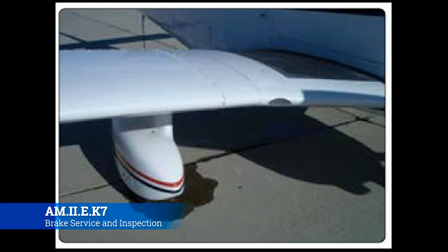And of course, if you ever see an aircraft brake leaking, it's time to figure out what's going on with it. You need to basically clean everything up first, and then start pumping the brakes to see if you can see any squirts of brake fluid anywhere, and then that will start to guide your thinking on how you need to fix it. Ensure that there's proper bolt torque on everything, proper torque on all your lines and fittings, and there should be torque stripe applied to everything so that you can see if it broke or fell off.